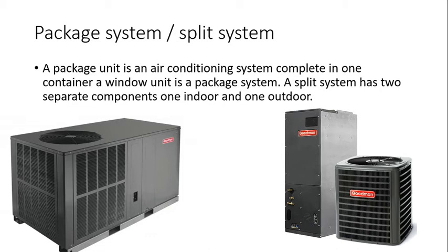Package systems and split systems. These are both Goodman setups. The one on the left, which is a package system, is exactly the same as the one on the right. It's just the components are in one box rather than two separate boxes. The package unit has some benefits. It's easier to install. I loved installing them compared to the split systems.